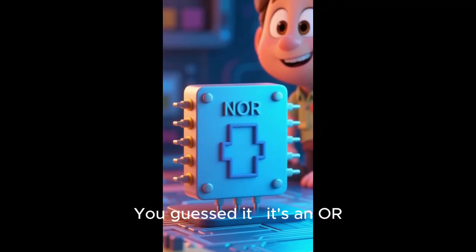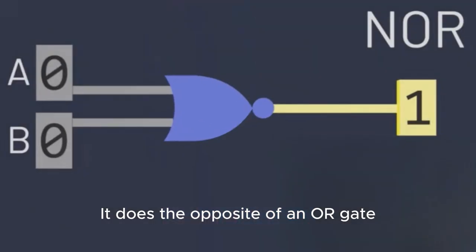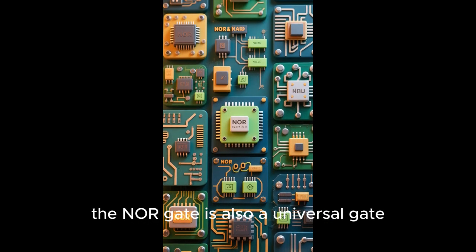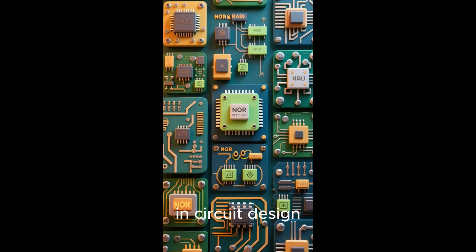Similarly, we have the NOR gate. You guessed it, it's an OR gate with a circle at the output, meaning not OR. It does the opposite of an OR gate. The output is 1, or true, only when all of its inputs are 0. If even one input is a 1, the output becomes 0. Just like the NAND gate, the NOR gate is also a universal gate, making it incredibly versatile in circuit design.